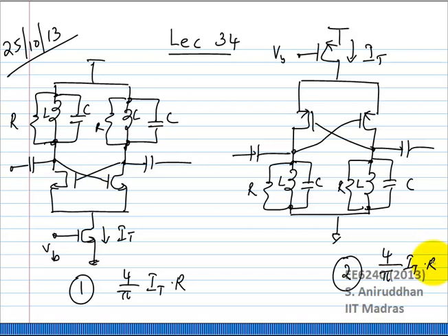No, we have not reached phase noise yet, right? So I am not even dealing with that. There is a difference in phase noise, but we are not dealing with that. Okay, so what will that give us? That may be a definite advantage, because you have separate N wells, you can actually get rid of the body effect. Correct? For the PMOSs. Definitely that is the thing.